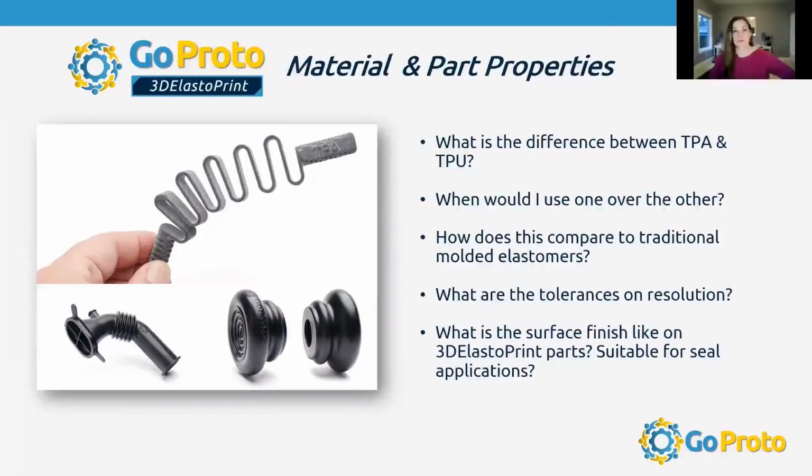The final question you had was on the surface finish, which you touched on earlier. One of the questions here as well is when it's vapor finished, is that all the surfaces, both inside and out? That's a good question. It is vapor, so it will tend to go toward the inside of a part. Like lattices that are difficult to reach, you couldn't mechanically get in there and polish them. It will get in there and reach. It's not forced by tubing. It basically flows into the chamber where the part sits, and it will flow where it flows. There's a fan in there, but it doesn't go directed. So sometimes it has a hard time reaching deep inside of a cavity. But most of the time, it will get in and reach difficult to reach places.